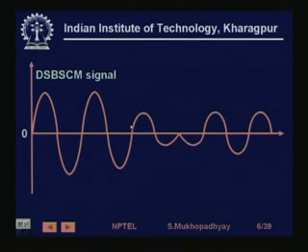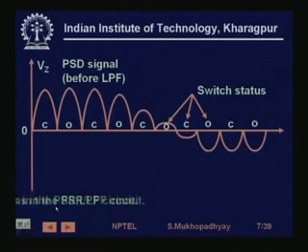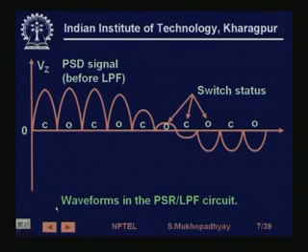The carrier frequency is shown to be much smaller because then the picture will become cluttered, but we can imagine that actually the carrier frequency will be much higher than this, but the waveform will be, if you draw the peaks, then it will resemble the motion, and since here there is a phase inversion, therefore the motion will be negative. So this is the modulated wave which we have to demodulate. So we go ahead. Now you see what's happening to this circuit.